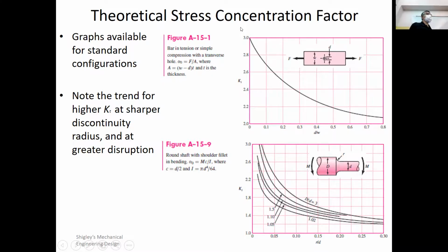If I overlook a stress riser, I may be designing a part that will fail because I am overlooking the stress that is doubled. So that's why these stress concentration effects should not be excluded. Of course, it really depends on the material and the type of loading, as I'm going to discuss in a minute here.